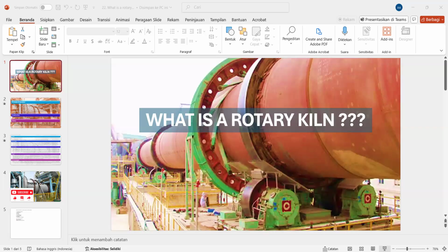Since the kiln is set at an angle, it also needs support to prevent it from walking off the support rollers, usually upper and lower thrust or trunnion rollers bearing against the side of the tyre, preventing the kiln from walking off the support rollers.